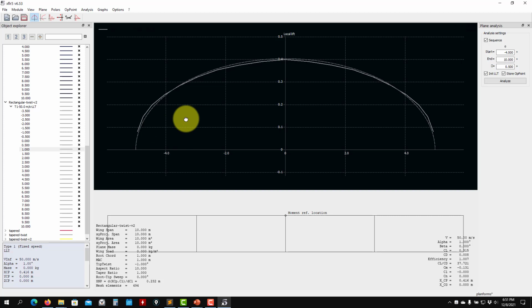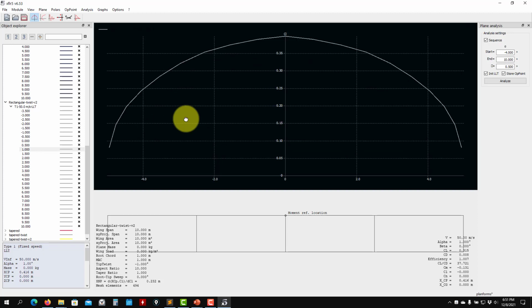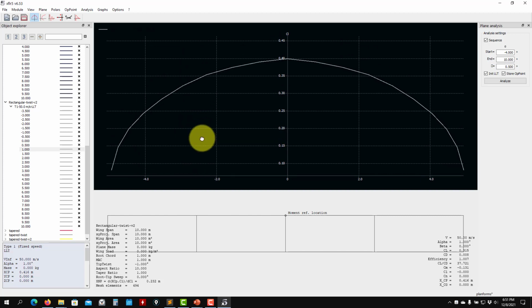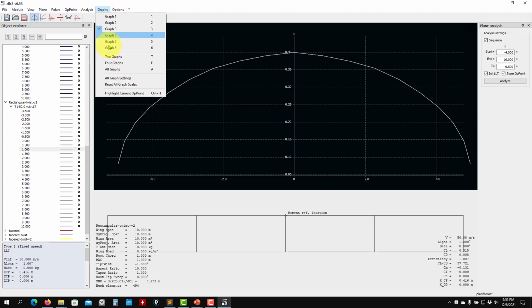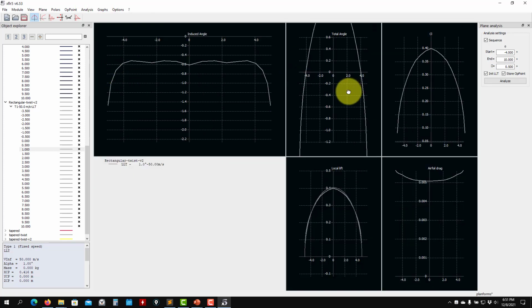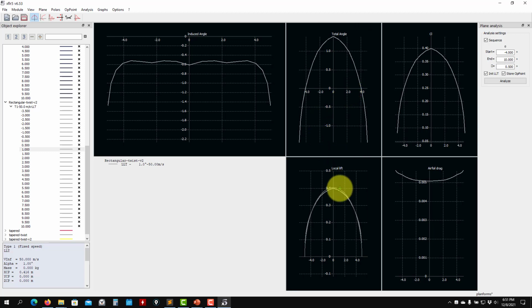So for instance, this is the only one where you can have the elliptical lift, but also when it comes to the coefficient. See that the coefficient also can get that elliptical behavior, and the circulation also. The circulation is related to lift. If you look at the Kutta-Joukowski theorem, see that it's related. So if lift is already elliptical, circulation will be as well.